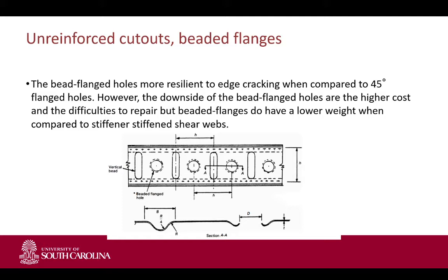And the idea is that you lift it up to ultimate load, so sigma ultimate, or the force that corresponds to sigma ultimate. Then your structure must be holding for 3 seconds, and after 3 seconds it may fail. But if it fails at, say, 2.998 seconds, that means you failed your test. So you have to go back to your analysis, see where the first failure occurred, which section it is, say halfway to the wingtip, for example, and you have to redesign that section. Or you need to come up with why it failed.